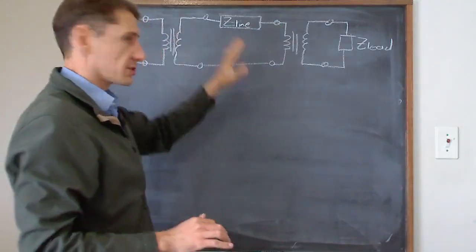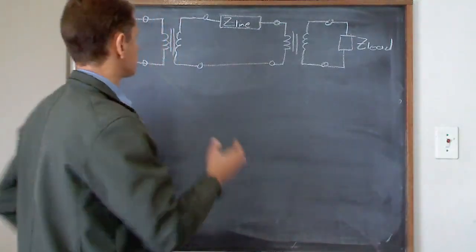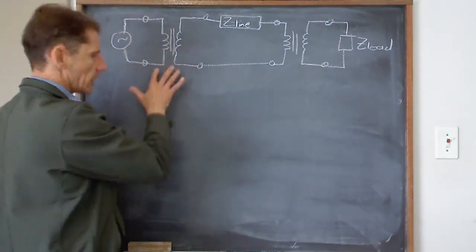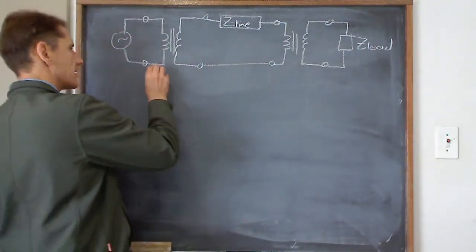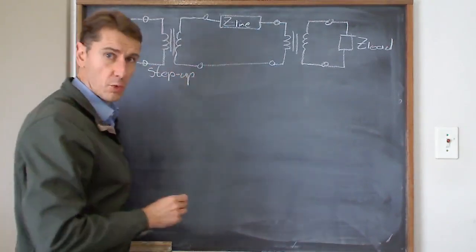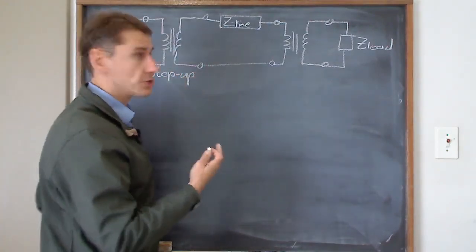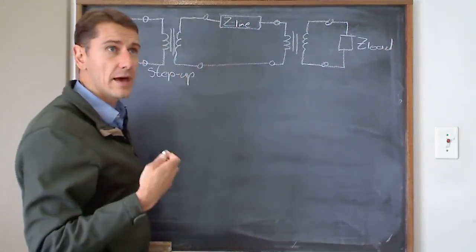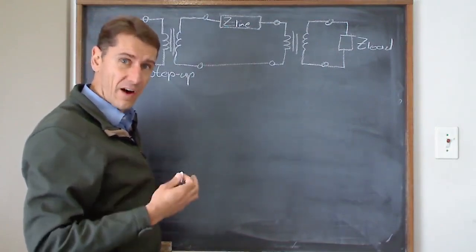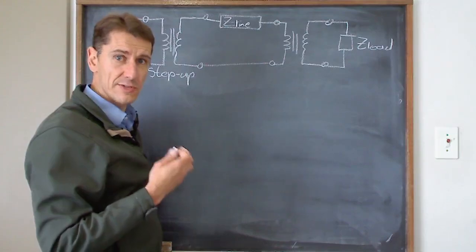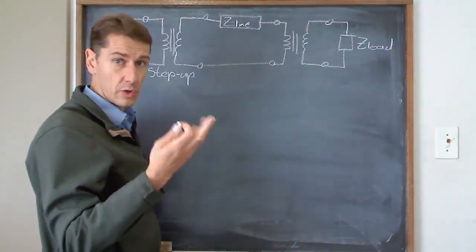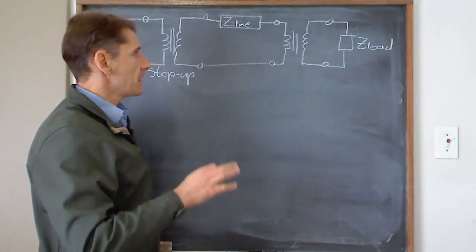So you're going to have losses. So how do we do that? You need to up the voltage. You get a step up transformer. It steps up the voltage to higher. So from here down to the Cape, they step up the voltage to 765,000 volts, 765 kilovolts. Three phases now. That's line to line voltage, three phase.